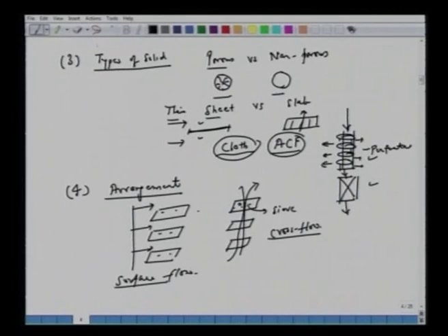So these are the introductory things we talked of. Mechanism, heat and mass transport, that's one. Drying is one unit operation where we have both heat considerations, transport of energy, and transport of mass. Different types of solids: porous, non-porous, slab, thin plates. Different drying rates, maybe same solid, charcoal, but one you have made into pellets, one into thin sheets, one into fiber. Different types of dryer arrangements, stacking. Then you have hot air, in some cases trays with perforations to allow the air to flow through. So it's a different type of thing.